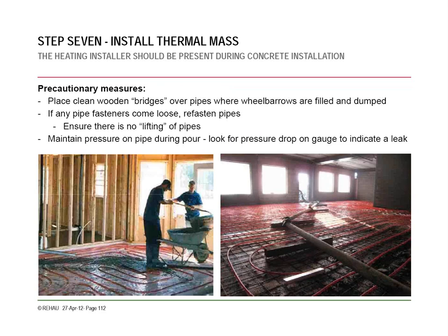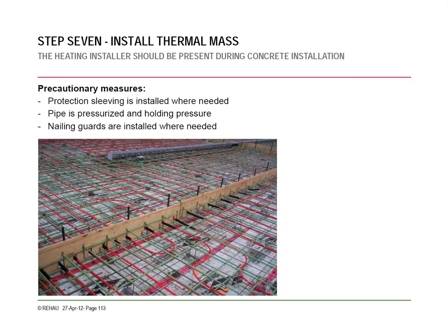Clean wooden bridges for wheelbarrows. Just more common sense things, you know, if you're going to be running stuff over the pipe, cover it. Protection sleeving where needed. Pipe is pressurized and holding pressure during the pour. Nail guards are installed where needed.